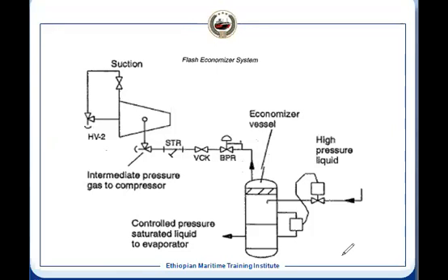Yeah. So this is the flash evaporator. The high pressure liquid is coming here, and this high pressure liquid will have the higher boiling point. And this is the saturated liquid, which is going to the evaporator.